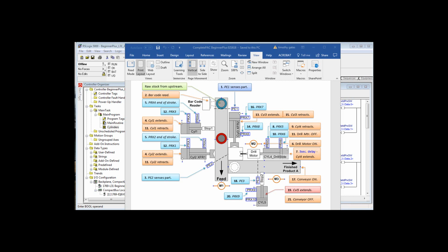Now, we don't need a delay there, because whether it's fully retracted or only partially retracted, we're then going to probably do another little delay. Another reason for delaying the extend, going back to number 8, is if you have done a lot of hand drilling, you know that it takes a few moments for the drill bit to auger out the debris, like a screw conveyor, an auger. It takes a little while for it to clear the debris out of the hole, so you want to leave it running.